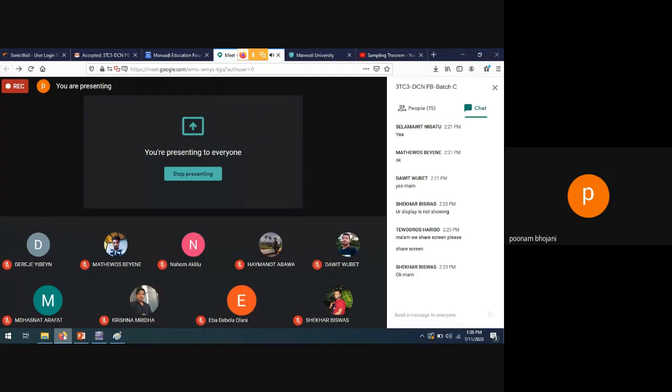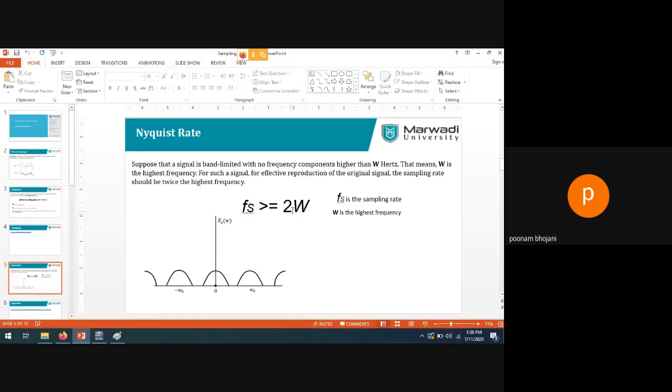They have taken so many examples and arrived at this conclusion that whenever they tried different data with a lower sampling frequency, they were not able to reconstruct at the receiver side, and that is known as undersampling. If you keep the frequency less than 2 of W, it is known as undersampling. If you keep your sampling frequency equal to 2 of W, it is known as proper sampling. And if you keep it greater than 2 of W, it is known as oversampling.